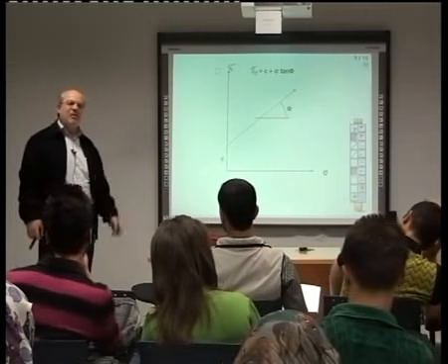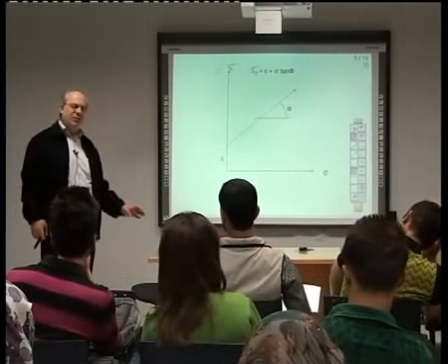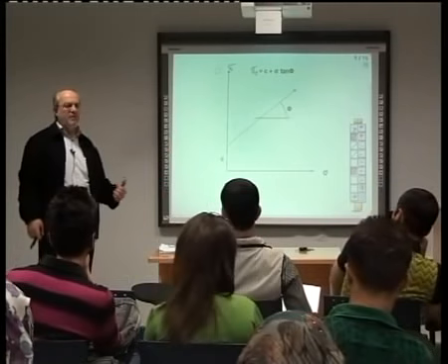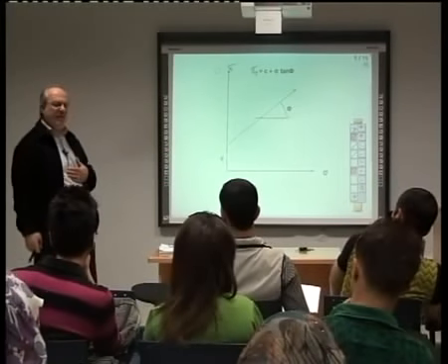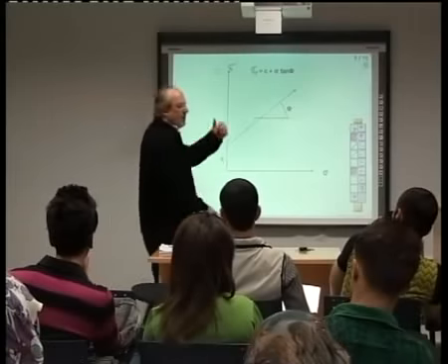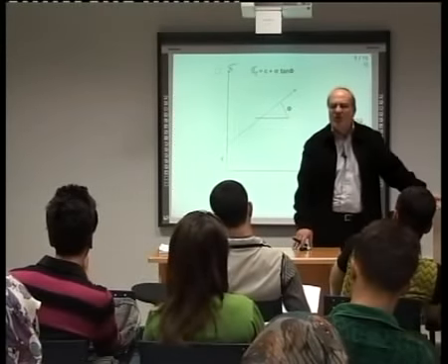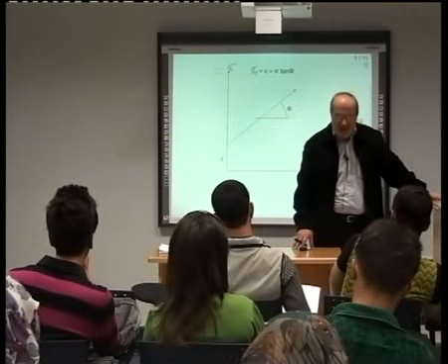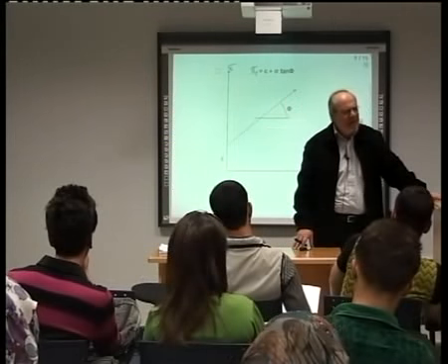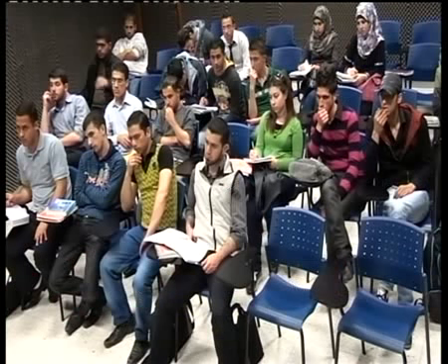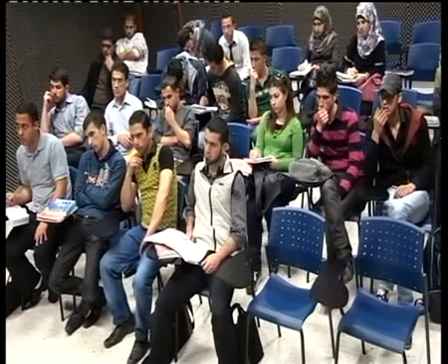That you see how much it is important to do sieve analysis. Because from sieve analysis I know how much sand I have, how much clay I have, and then I will expect whether I will have more friction to give strength or more cohesion to give strength. You see? I don't have cohesion at all in sand. No cohesion.